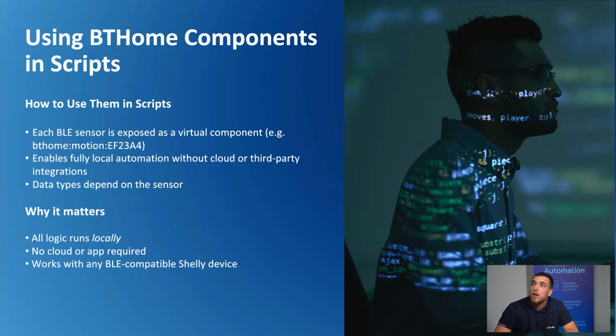Let's say once the Shelly device output is activated and is on, you want to send an email to someone. You cannot do this through the cloud app. You cannot simply do it by a URL action in the Shelly web interface. However, with scripts, you can use third-party services to send that email.